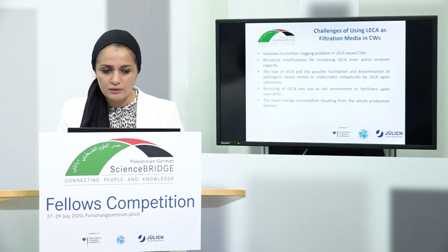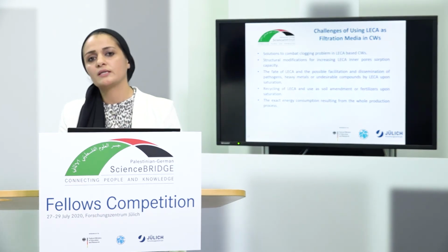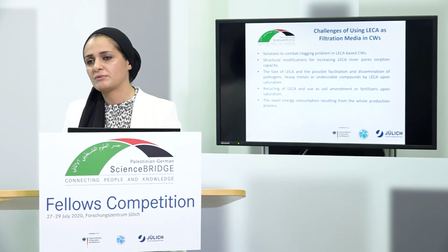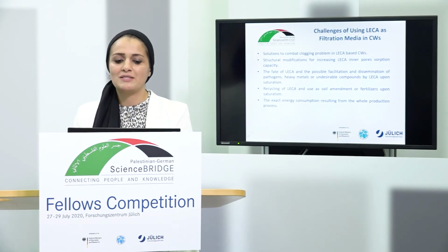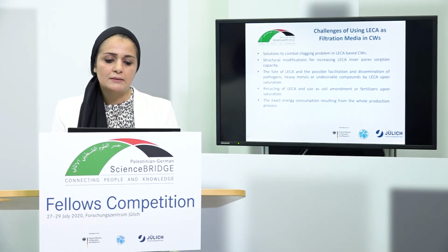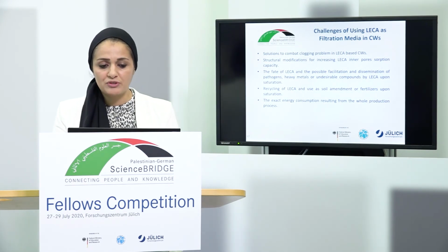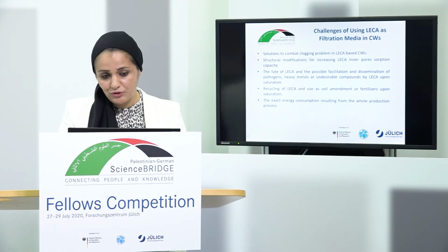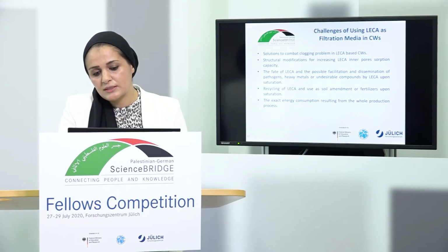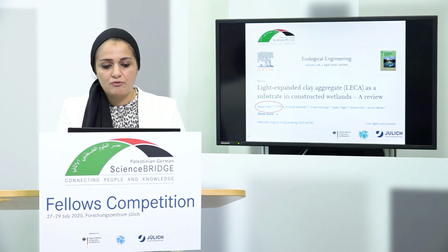What would be the fate of LECA if we use it for absorption of toxic substances? Where do we go with this material? It's already a toxic material. And of course, there is the question of recycling and using this material as an amendment or fertilizer upon saturation. There's also a question of energy consumption, because it is manufactured at high temperature, and this costs energy.